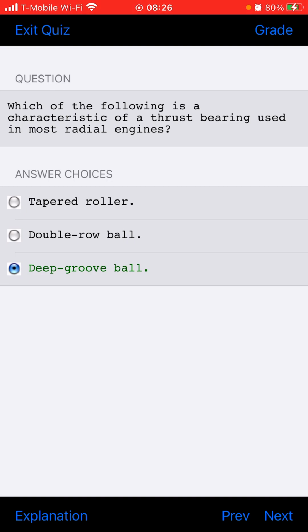An increase in the manifold pressure with a constant RPM will cause the bearing load in an engine to increase. The cylinder pressure applied to a crankshaft through the connecting rod bearing is determined by the compression ratio of the engine and manifold pressure. If the manifold pressure for a given RPM is increased, the bearing load imposed on the crankshaft will increase.